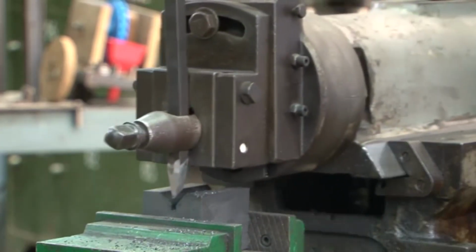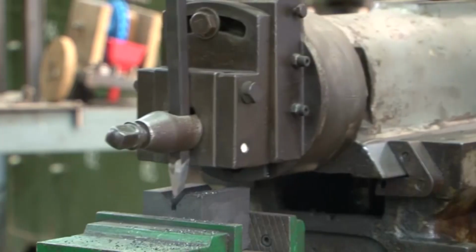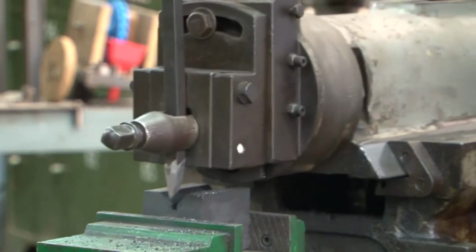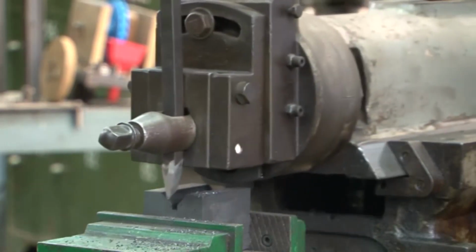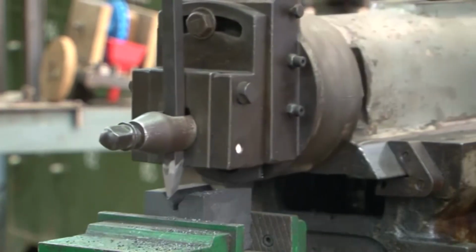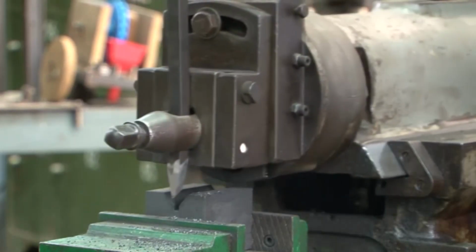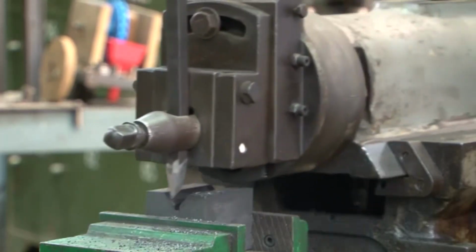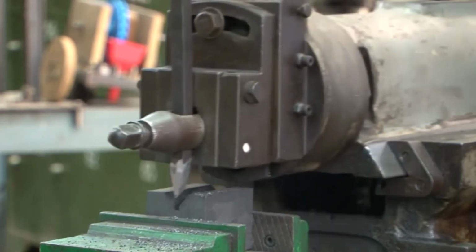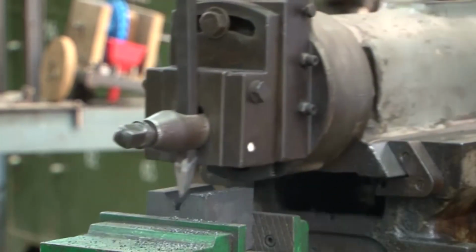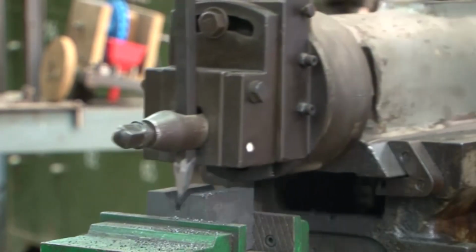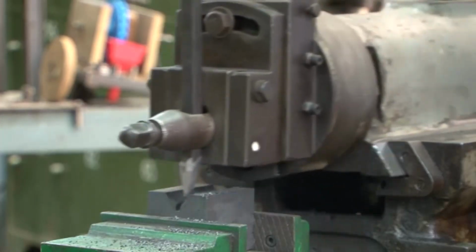And notice one thing, that during the backward movement, the time taken for the backward movement is less, because the backward movement is at a higher speed than the forward movement, since at the backward movement no material has been removed, all right. And during the backward movement, as I have shown it to you, the tool is lifted up if required. So, if a very high depth of cut had been given, you could have seen that the tool is being lifted up. Here it may not be visible very well that the tool is still being lifted up while the tool is moving back.